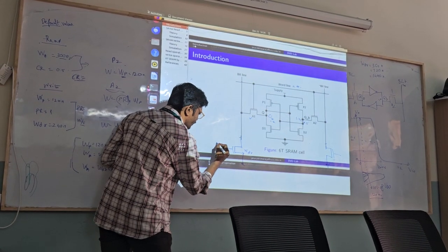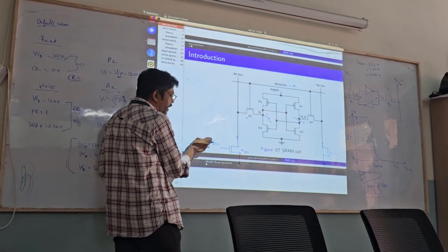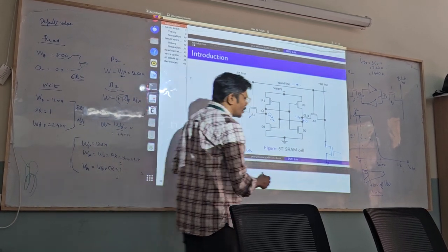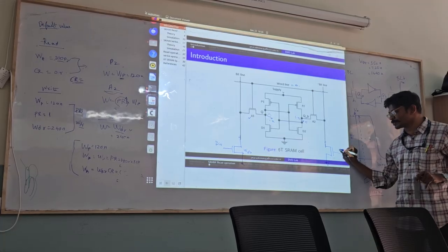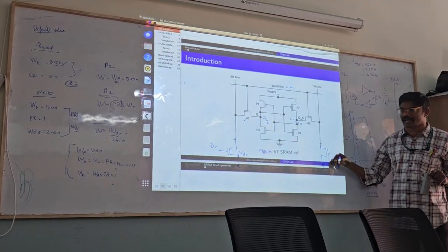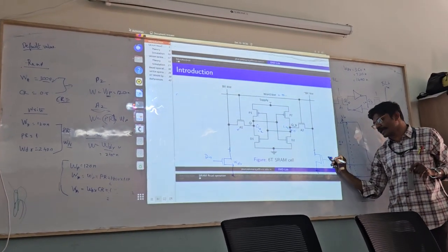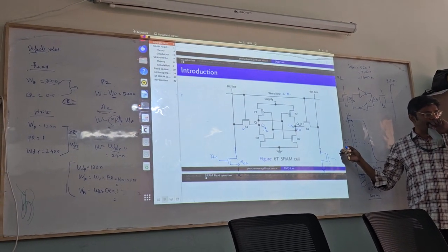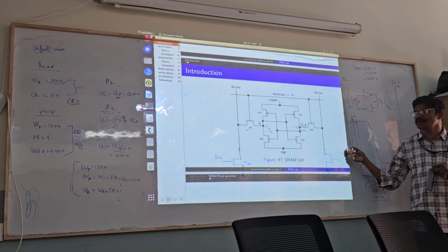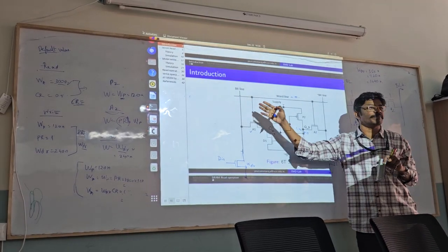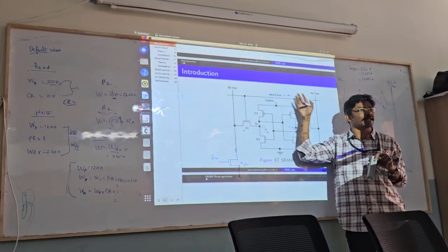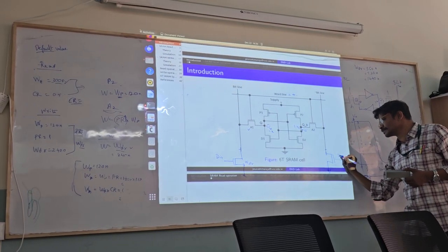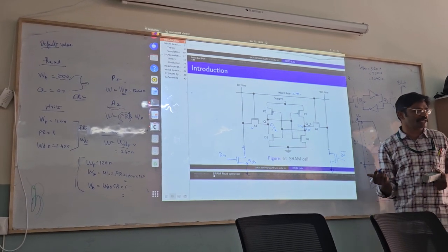Say for example, if my DN is applied here as a gate input for the bit line, what is the label that I need to substitute here to drive the driver of this bit line bar? Can I apply the same DN or is it supposed to be different? What is the meaning of this? Bit and bit bar, or basically bit line and bit line bar, are complementary in nature, which means even the data in that I am trying to force is also supposed to be complementary in nature.